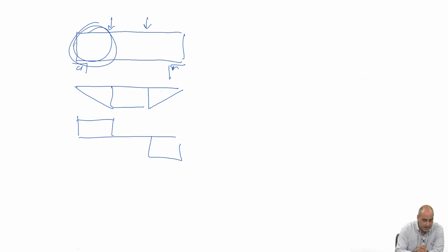So they observed cracks like this, inclined at 45 degrees. And most of all, they observed that whereas the bending crack started from the bottom and propagated towards the neutral axis depth, the shear crack started from mid-depth of the beam. And why was this?